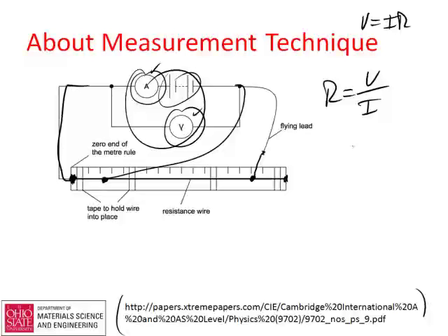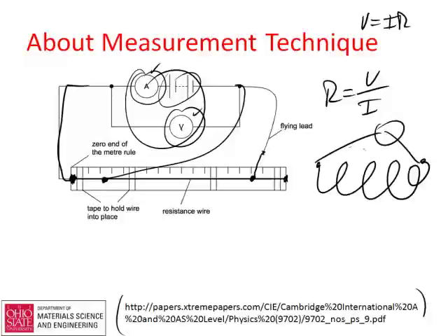Or you can just take your wire, take a long enough lead of it, put an ohm meter across the two ends and measure that, and that's probably more likely what you would want to do. The trouble with simple ohm meters is usually there's some contact resistance on the order of a half an ohm, and usually the first half ohm isn't always so accurate.